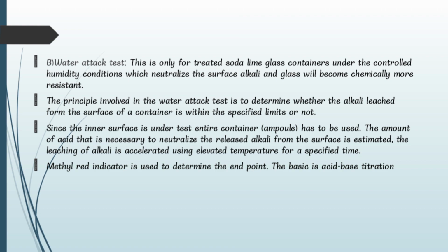Since the inner surface is under test, entire containers have to be used. The amount of acid that is necessary to neutralize the released alkali from the surface is estimated. The leaching of alkali is accelerated using elevated temperature for a specified time. Next, methyl red indicator is used to determine the endpoint. The basic analysis is acid-base titration.